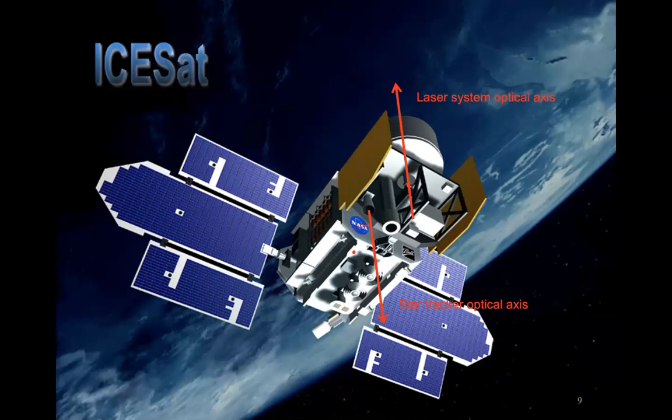Let's do an example. When you want to determine the orbit of the spacecraft, you also need to know the attitude, because the attitude will change the perturbative effects. Let's assume a satellite around the Earth. You have to know the attitude of the solar panels in order to determine the drag effect.